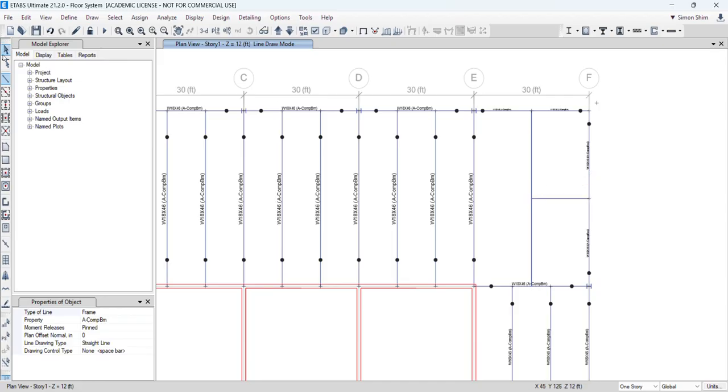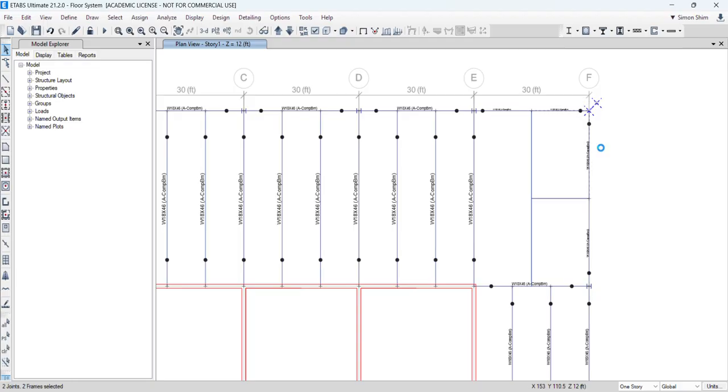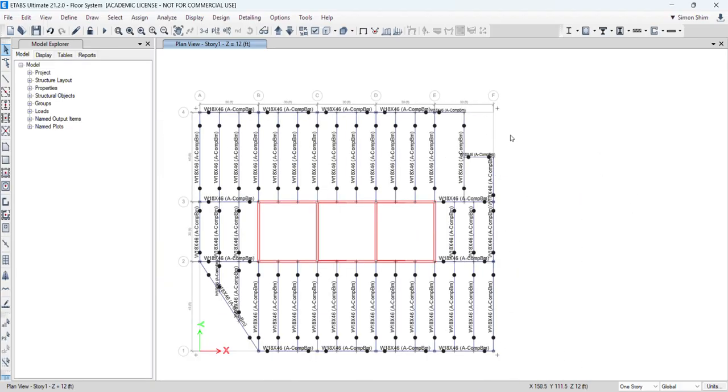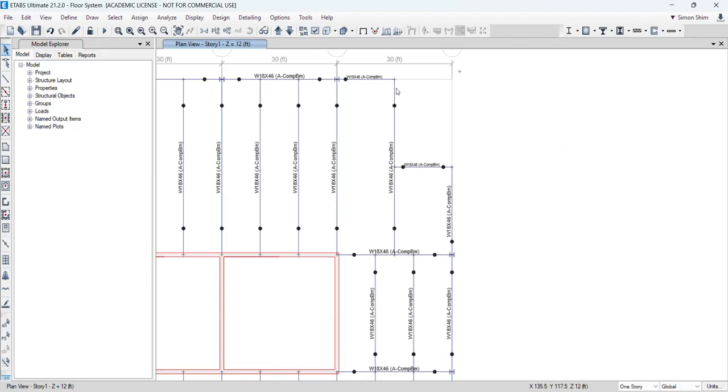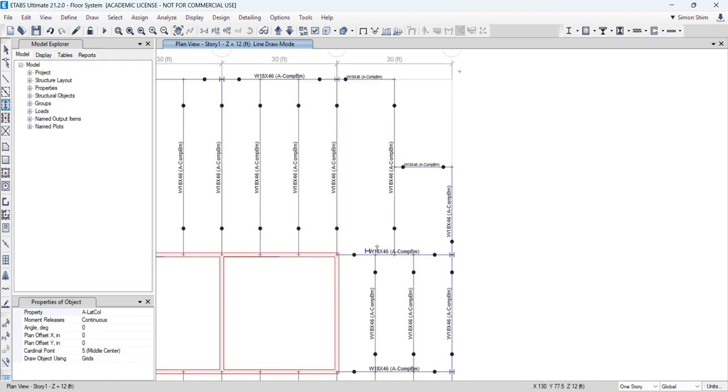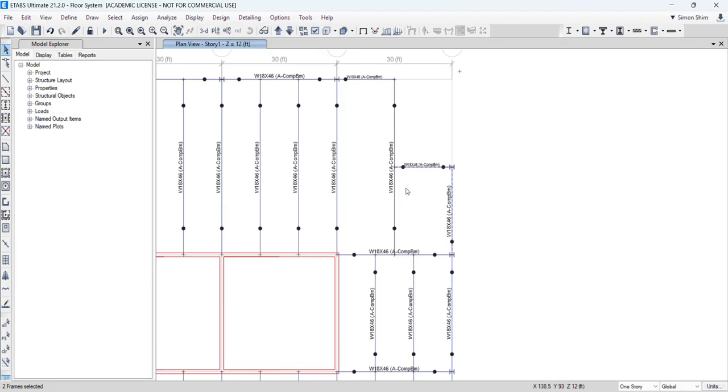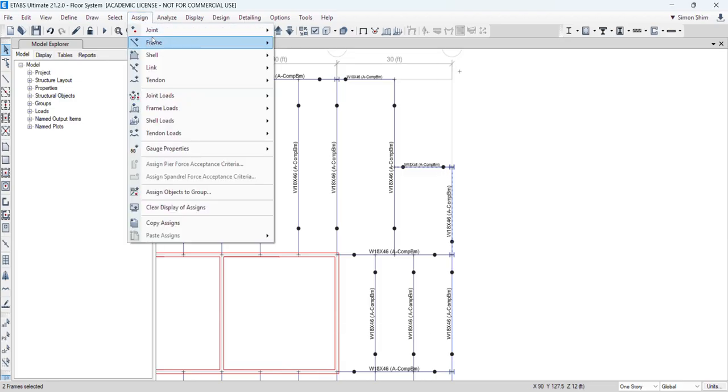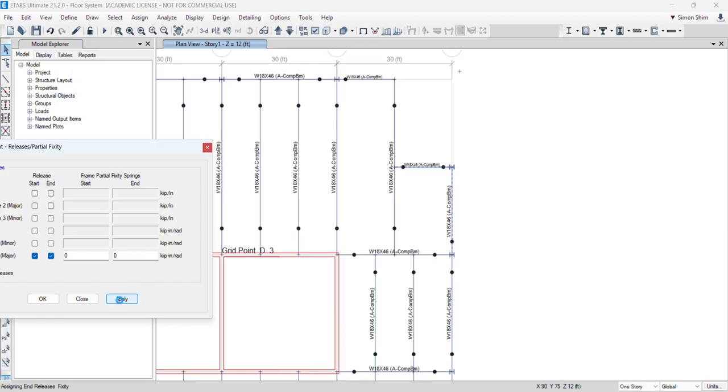Okay, right? I think it's the last class, so we talk about something non-typical. So let's say you have this situation, right? Obviously you may end up with this, or this is a cantilever beam, and this cantilever beam is too long. So you may end up with a different approach. But here I'll assume adding a column here. So this one is a girder, so I need to make a moment release. So this one, okay, tied together.